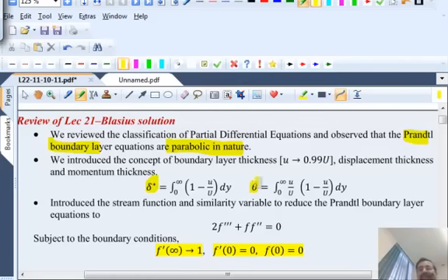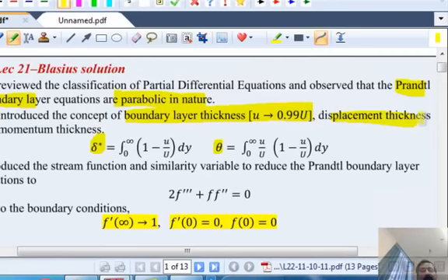The boundary layer thickness, which is simply the distance over which the velocity reaches 99% of the free stream velocity. And then the displacement thickness, which is defined as the thickness by which the fluid has been displaced with a uniform velocity and zero velocity near the plate. And momentum deficit is the same idea. What is the deficit in momentum between the inlet and outlet? And that is caused by the drag on the plate. And we are going to use these two definitions today in developing something called an integral method.